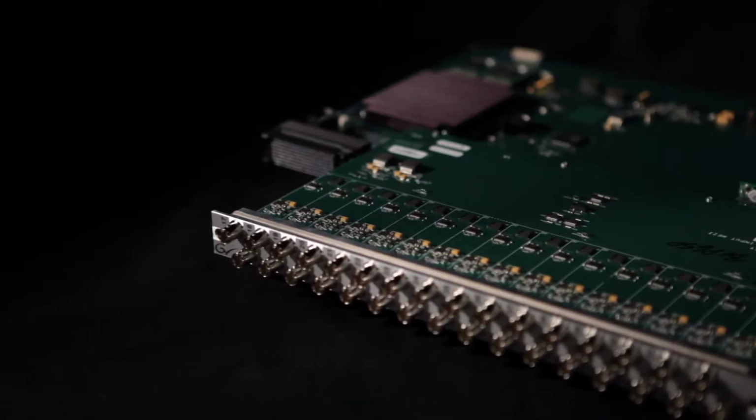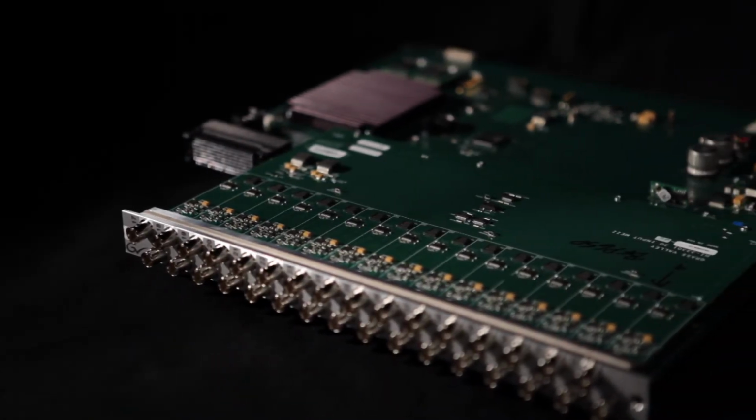Keeping the input circuitry close to the input connectors helps to isolate the interfering signals and minimize the effects of crosstalk at the switcher inputs. This is a key advantage in reducing crosstalk and signal losses between the rear panel and equalizers. After the signals pass through the equalizers, they are all the same amplitude, and crosstalk is not as serious in the rest of the system.